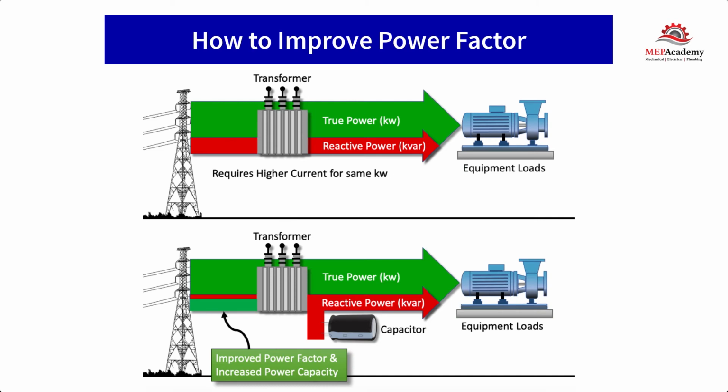How to correct poor power factors? How does a building owner go about correcting their power factor to reduce wasted energy and cost while increasing distribution and transformer efficiencies? By adding capacitors to the system, where induction motors are the main cause of the problem, the building can improve its power factor and network efficiency. The effect of a capacitance is opposite that of inductance.